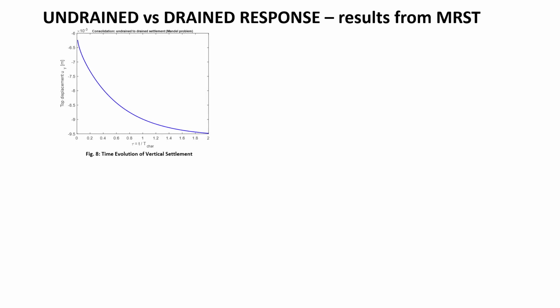On this slide I'm showing numerical results of a Mandel problem simulated in the MATLAB Reservoir Simulation Toolbox. These plots illustrate how the material transitions from an undrained response immediately after loading to a drained response as pore fluid diffuses out of the domain. I'll walk us through each figure, explain the axes and highlight the physics behind the result.